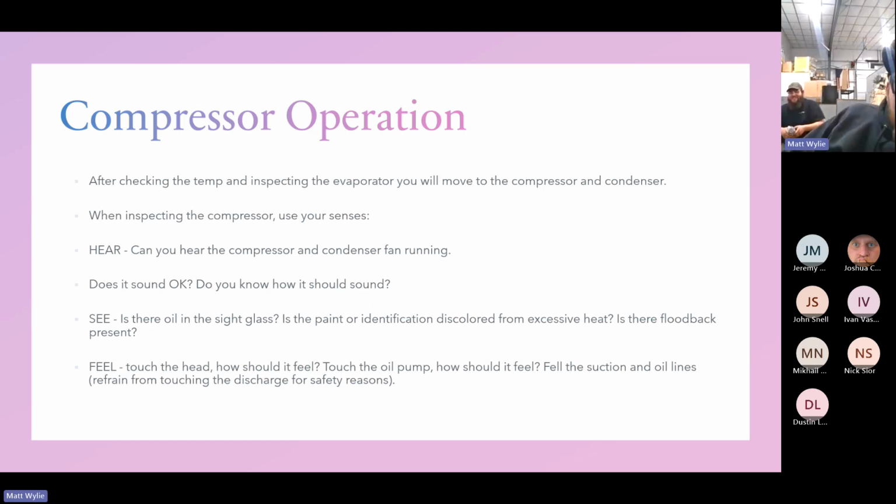Check compressor operation. After checking the temp and inspecting the evaporator, you move to the compressor and condenser. When inspecting the condenser or compressor, go back to your senses. Can you hear the compressor? Is it running, or is just the condenser fan running? Or if it's a scroll, is it in reverse?